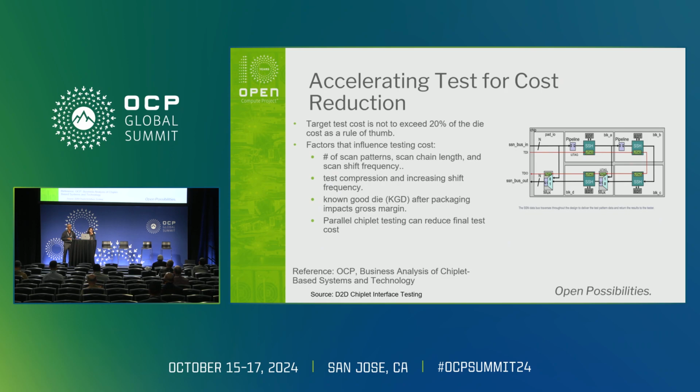With so many features to test, and also different combinations of chiplets that can be tested in a multi-die system, the test cost can be huge with respect to what all needs to be done. And test cost reduction can be achieved by limiting the test time, where techniques like e-test patterns that are compressed and sent over the SSN buses at a very high speed can be made useful to reduce the test time.